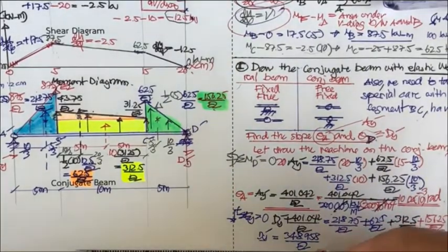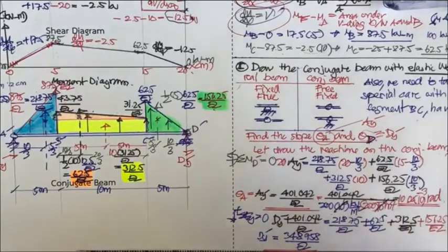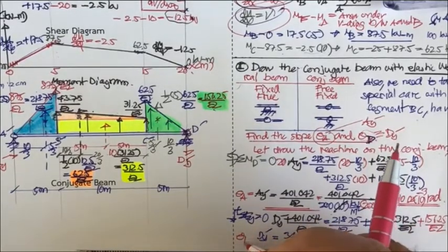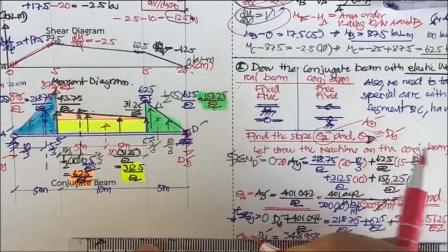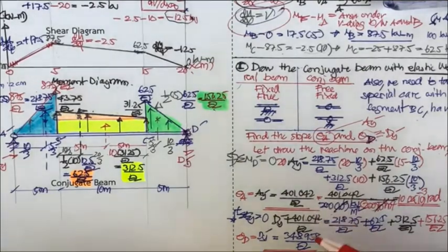Okay, this is going to be our result. That is going to be theta sub d, the slope at D. You can see the slope at D is smaller than the slope at A, as my assumption. What is the assumption? Since the force near A is 20 kilonewton, larger than the force near D, which is 10 kilonewton, the slope at A is larger, so it's correct, okay?